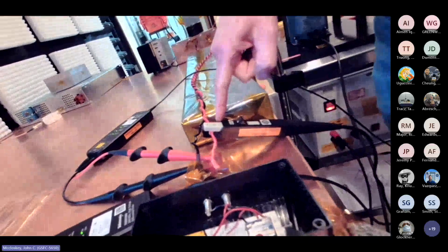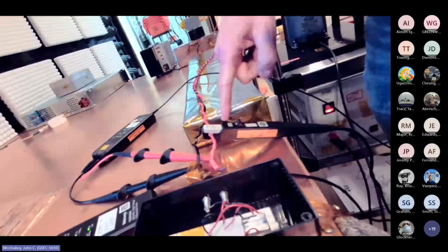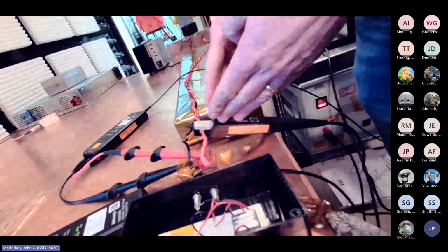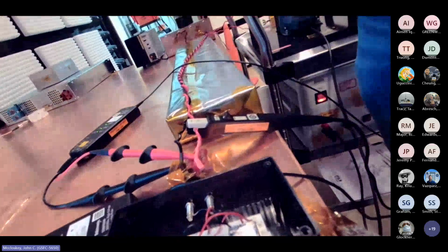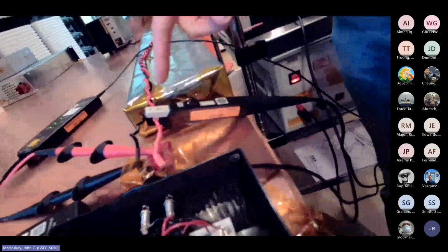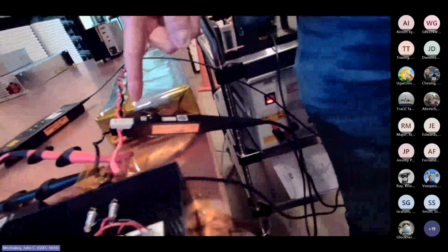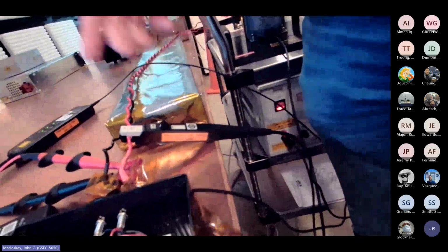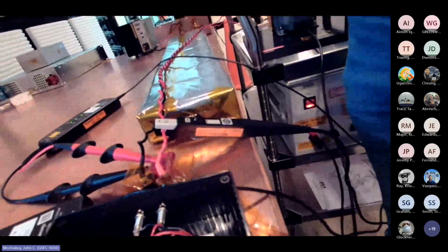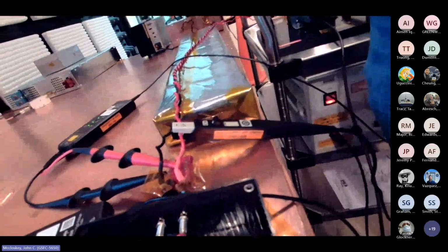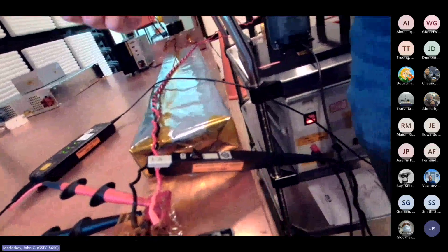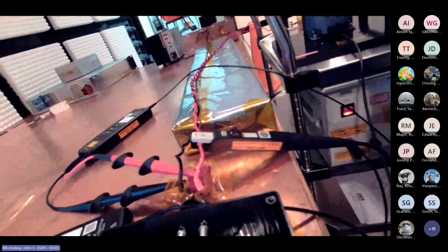And as I said Monday, I highly recommend not only monitoring the current, but actually incorporating it into your controller. Because that's the best way to tell, are you getting into a high current condition? You're actually looking at the current and you set the current limit to the 4 amps. That corresponds to the 1 volt limit into the half ohm load.